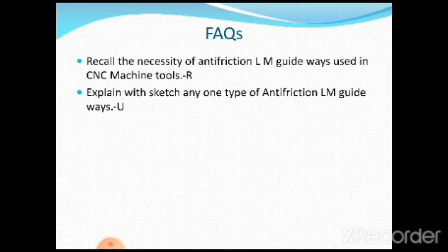Aerostatic guideways have limited applications. The basic application is in the coordinate measuring machine as a major application, because there it can be used only for positioning purposes, not for continuous movement, as they have lower stiffness. So that is why we need to understand these applications.